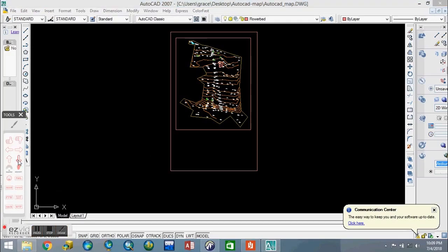After exploding, we need now to select our line that we want to extend. So you'll use this one. You click on this, extend. Then first we are going to select the lines where we want our line to be extended to. So you want to extend this bottom line towards this side and towards this side. So first you'll click on the ones you want to be extended to. Click on this one and this, then on your keyboard press enter.